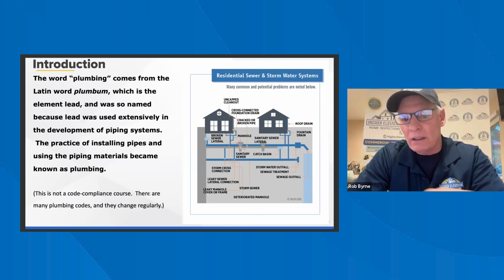Right, in the connection of the water distribution system to the water heater appliances, there is a potential for migration of heated water into the water distribution piping. In a typical water distribution system, the water will expand into the public water system. Expansion is not accommodated in this system.